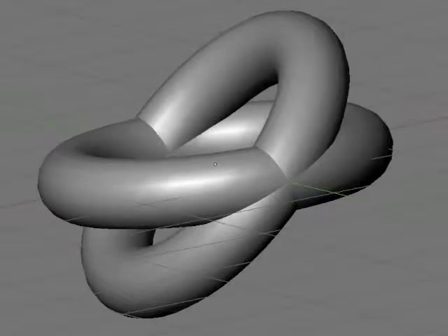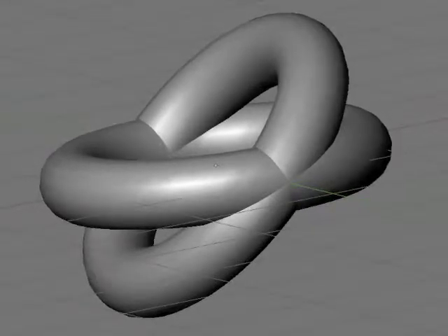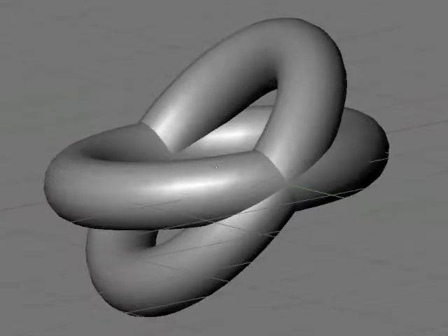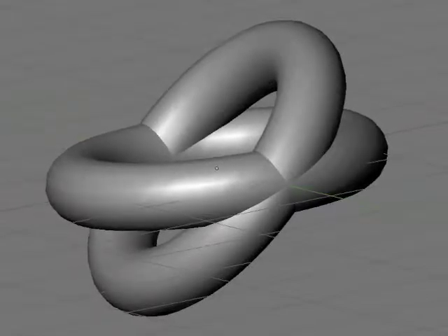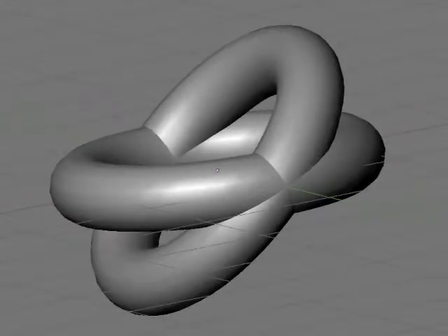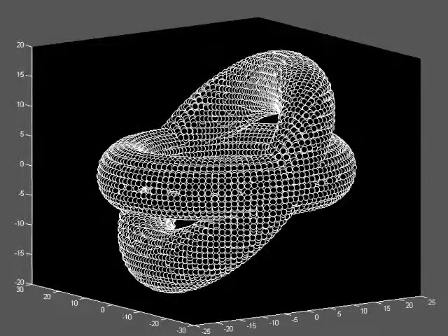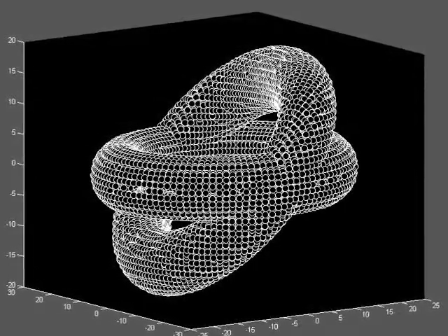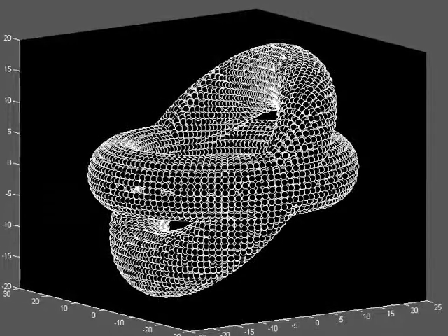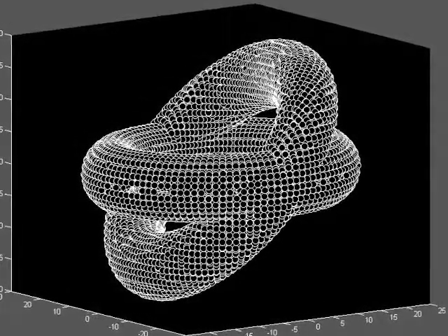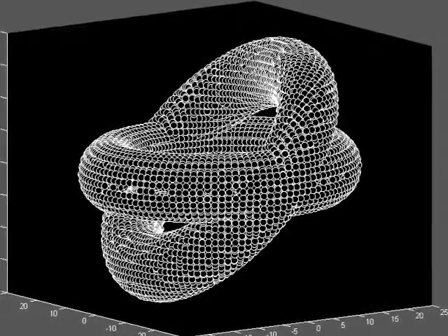My name is Kucera and I'll be covering the software section. The software of this project was divided into two main objectives. The first objective involves transforming a 3D model into usable data, while the second objective involves writing the code to display this data on the LED board. The transformation from a 3D model into a usable form starts with the creation of the 3D model. The models used in this project were created with the free 3D model software Blender and exported in the DirectX file format. This format lists all the vertices and edges in plain text, making it much easier to parse.